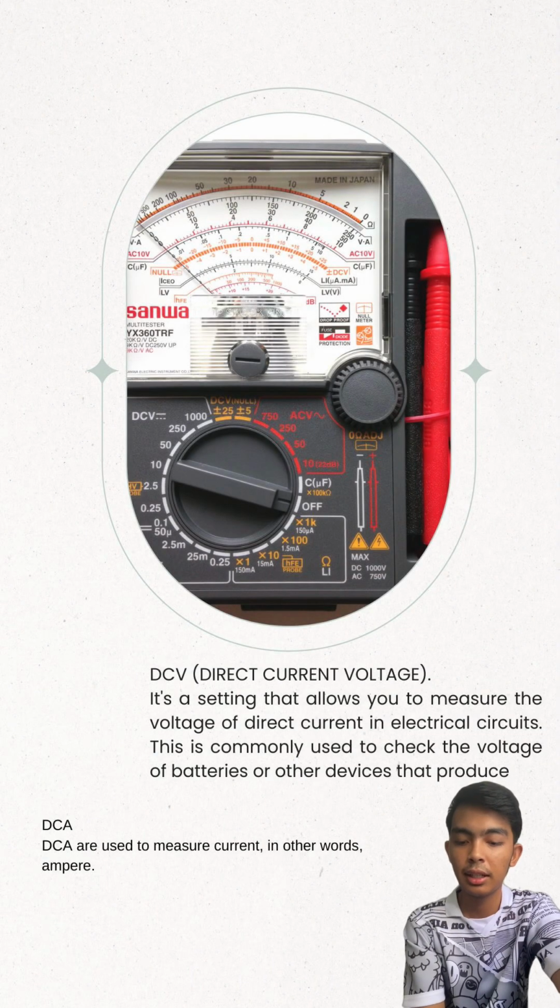DCV, direct current voltage. It is a setting that allows you to measure the voltage of direct current in an electrical circuit. This is commonly used to check the voltage of a battery or other devices that produce DC. DCA is used to measure current, in other words, ampere.